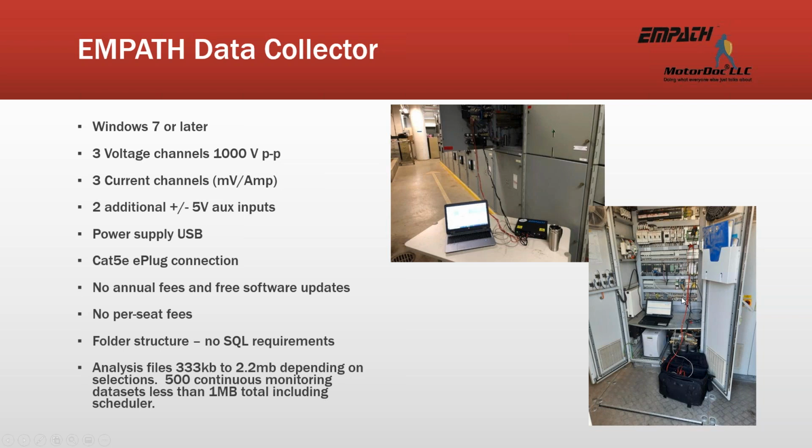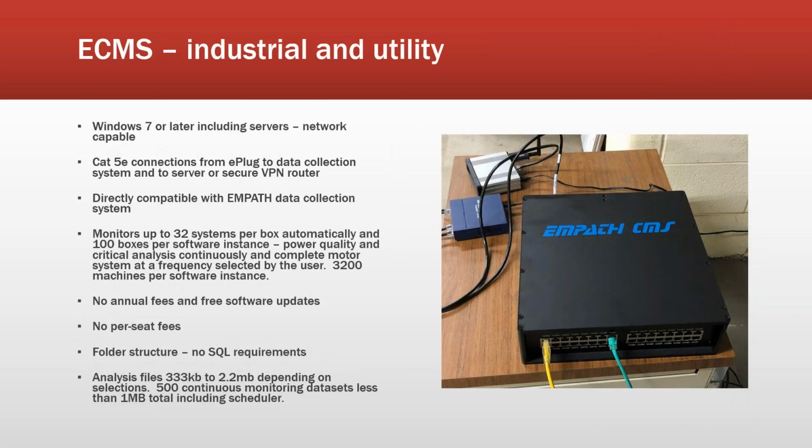Lower right here, this is actually an S97, so a Suzlon DFIG versus their SFIGs. We did a number of sites. There are not a lot of those out there, but they're a nice low wind machine. We found it's far easier to collect on the low voltage side. So I'd say about a majority of our work is collecting data on the towers and then analyzing it. And of course, being the lazy engineer that I am, it's almost all automated now. So we'll cover that a little bit as well.